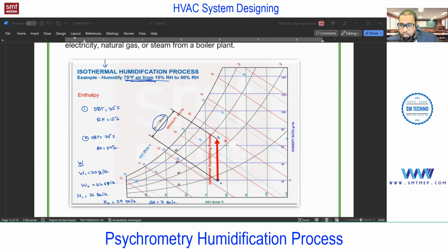Heat is utilized to change the phase of that water. We are providing the moisture, this steam. To convert that water to steam, heat is required. So we're adding this 7 BTU of heat to the moisture so that it can evaporate and mix in the room so that the RH increases.